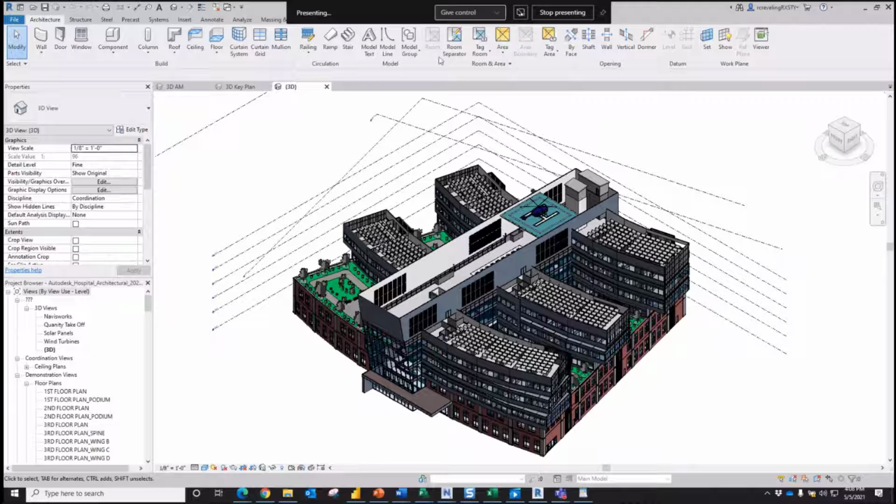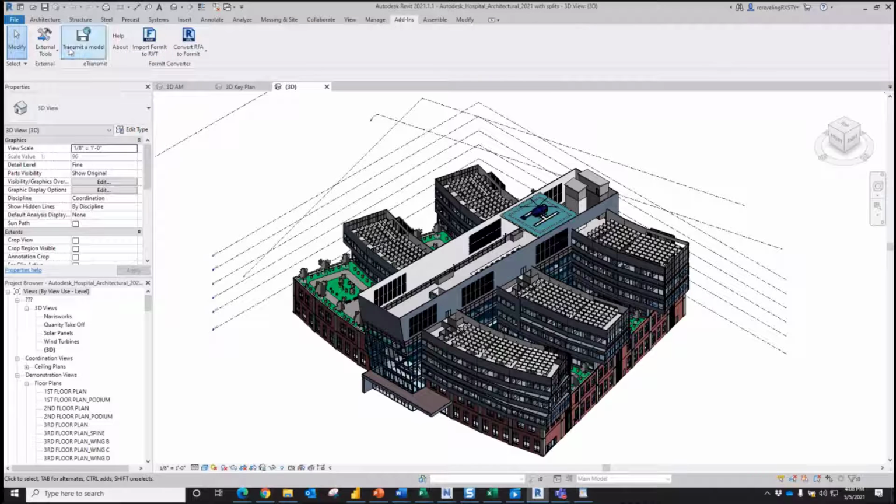As we proceed, I'm going to first publish this model to Navisworks. Navisworks is going to be my simulation environment in this exercise. Additionally, I'm going to publish my model from Revit to a software called Assemble that is part of the Autodesk Construction Cloud. From Assemble, I'm going to publish schedule activities and Navisworks selection sets, and bring it all back together in Navisworks. So let's review the Assemble application now.